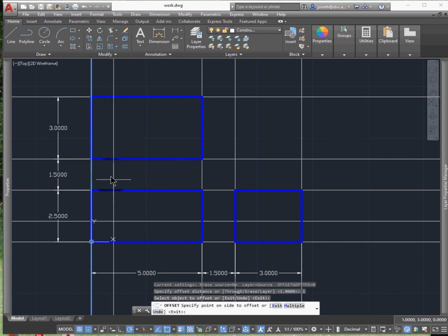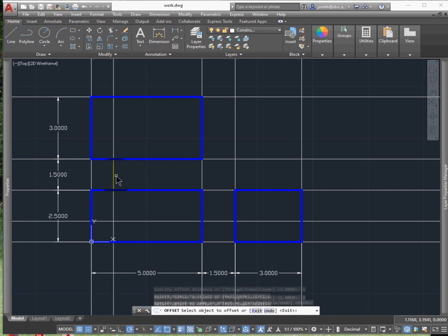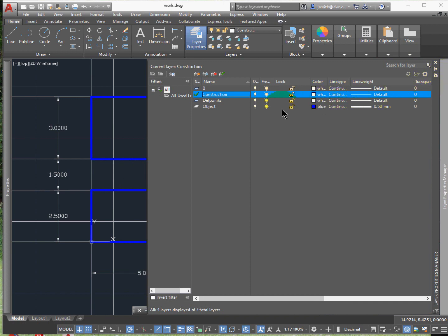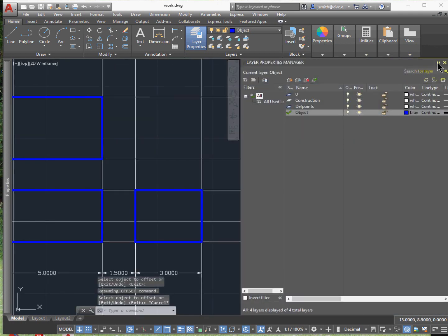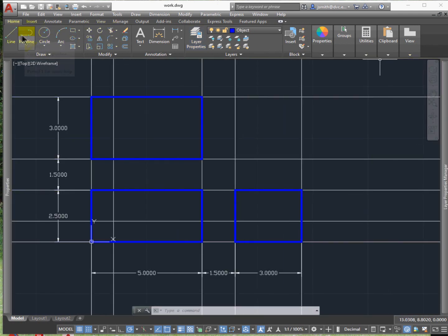And so essentially what I'm doing is I'm looking at my drawing and I'm making the parts so that they're all going to be consistent in the top, front, and side views. And so you can see I'm adding the lines because this is in the object portion. It's got the proper line weight.